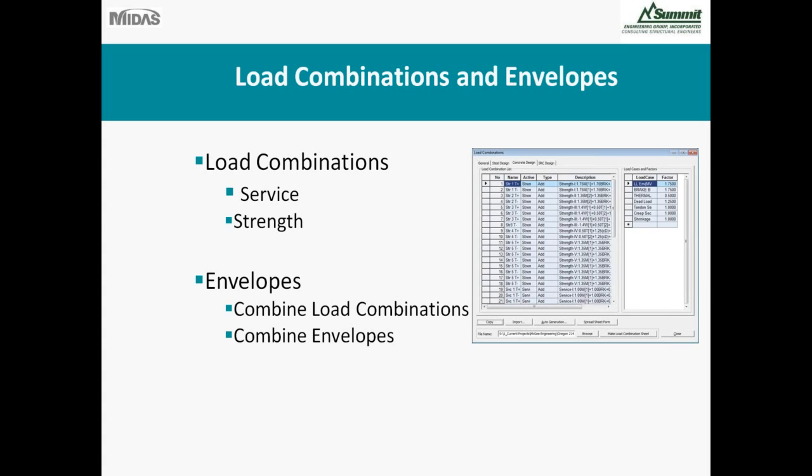I certainly divided that back out to gain an understanding of what the controlling load combination turned out to be, but to get a quick check of what your ultimate moment is or what your maximum service stresses are, it's handy to be able to combine all the envelopes together and just click on one button once the model is run and your performance checks.